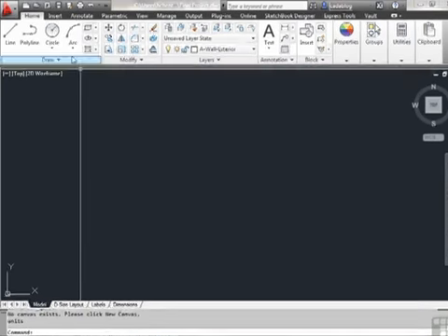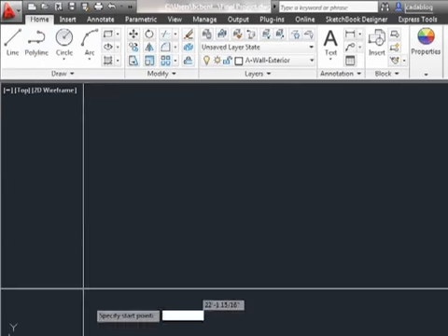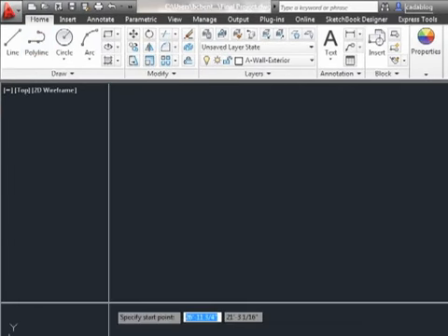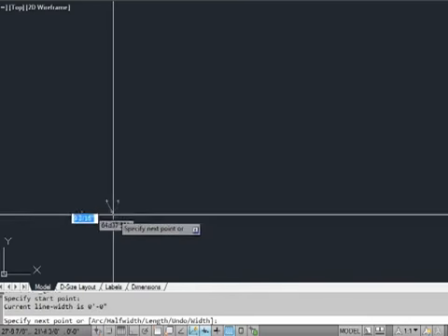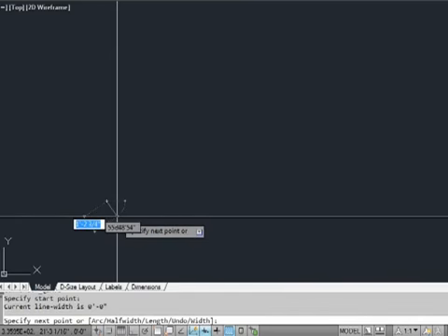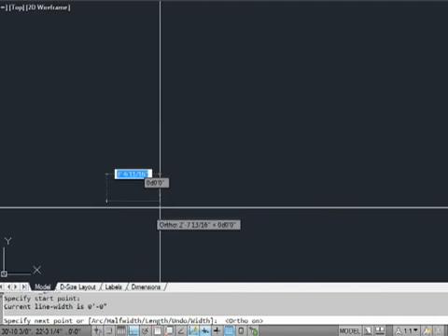Start by using the polyline command. And you can start this drawing anywhere. Make sure you're drawing it in model space because that's where the model belongs. Pick a start point for your wall and turn on your ortho command. That's going to make things a lot easier. Our walls aren't fancy. They're at right angles.